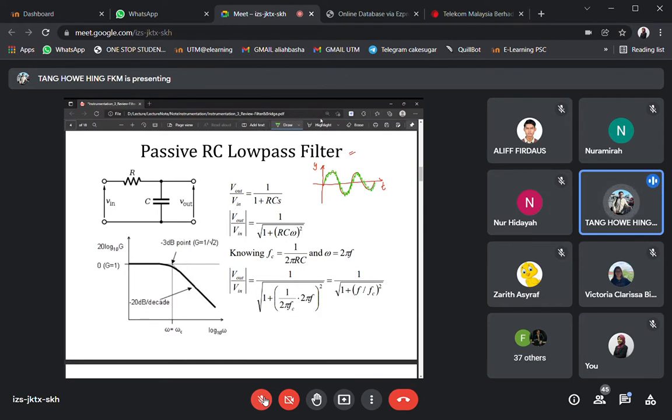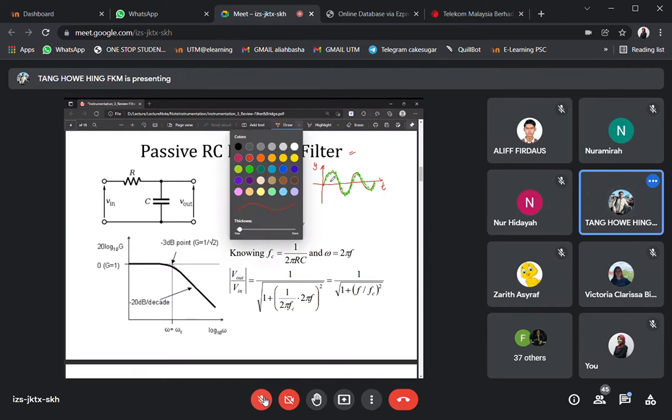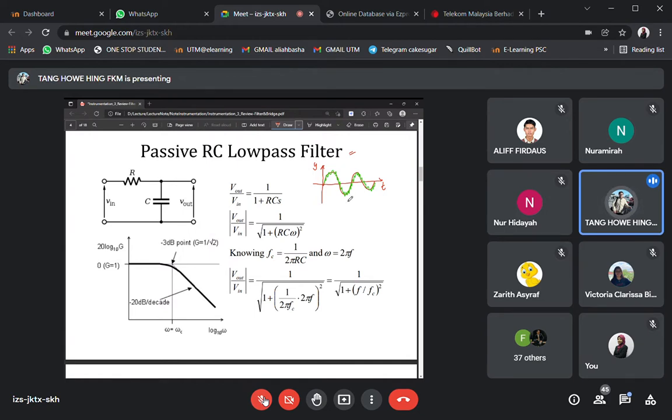So you can see that if we do the spectral plot, or we perform Fourier transformations, okay, fast Fourier transformations, and then try to get the spectral plot of this graph, most probably we are going to get two plots. So after we perform the Fourier transformations, instead of representing it in the time domain, right now we are representing it in the frequency domain. Okay, so this is a frequency domain, and then the y-axis will be the magnitude.